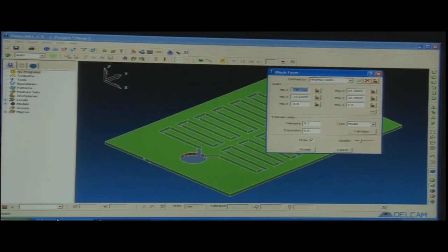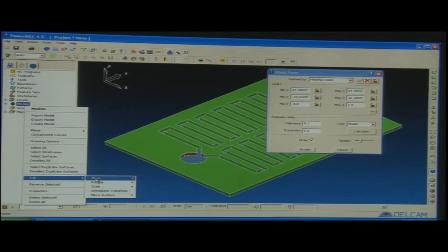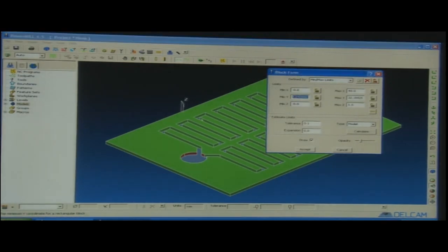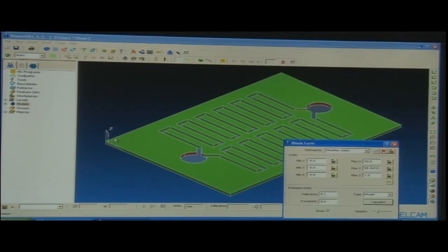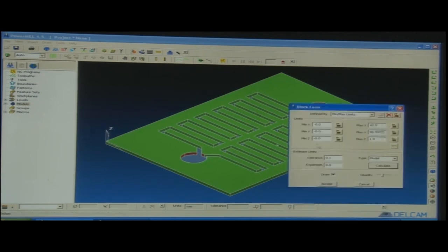So, this is 0 0. Now, we can see this is 0 0 of our workspace, let us say x y z 0 is here, and this is the corner of our block. We need to match this center here. So, we move x to 0, we move y to 0, and we have also moved z to 0. Now x 0, y 0, z 0 makes the origin of the workspace, and the origin of the workspace and the corner are now matched.